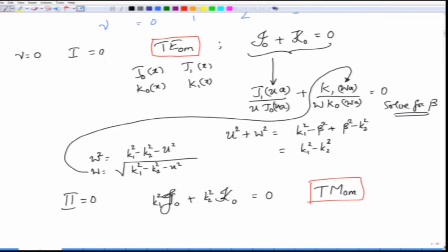When you take nu equal to 0, I said that the modes are TE0M. It means that the electric field component Ez actually vanishes, Hz will be non-zero, and depending on the other one, all the other components are present. Okay. Now, look at what is happening.